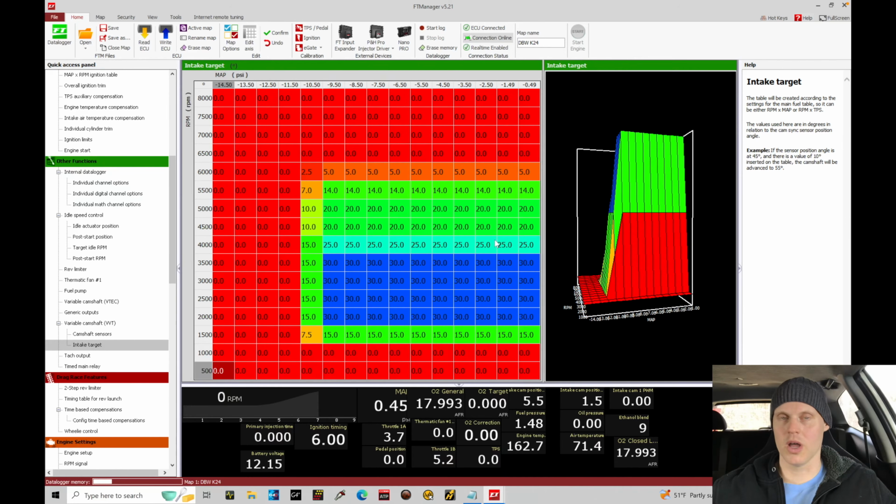What we're going to do here is actually lock our VTEC on at 3,000 RPM. That's the lowest you can safely lock and engage VTEC, because you need at least 50 pounds of oil pressure at the cylinder head for VTEC to positively engage. Now, I'll lock VTEC at 3,000.